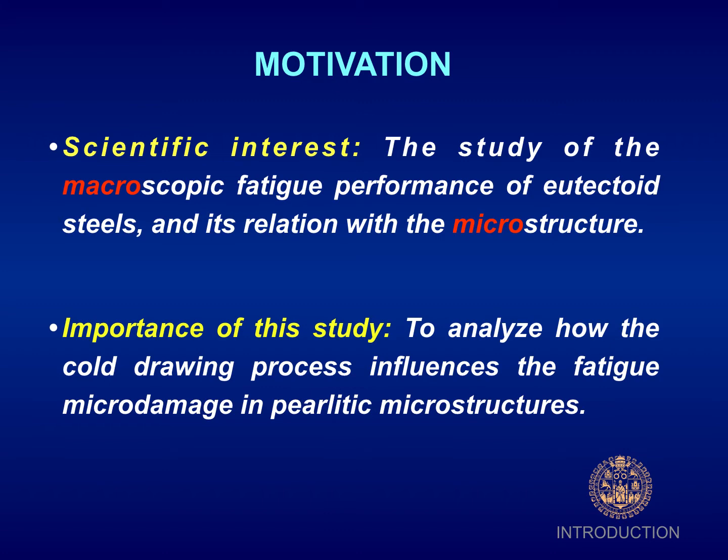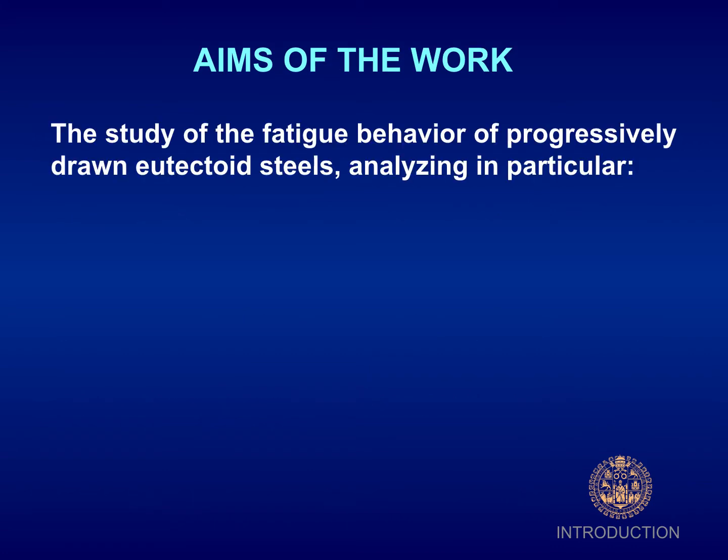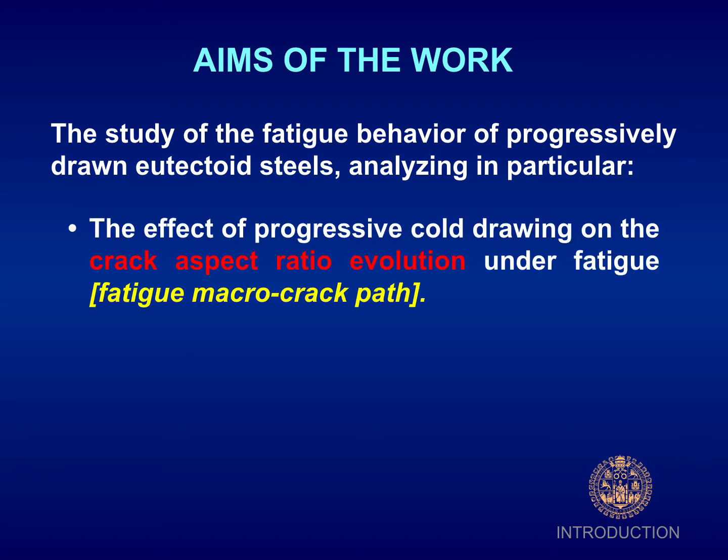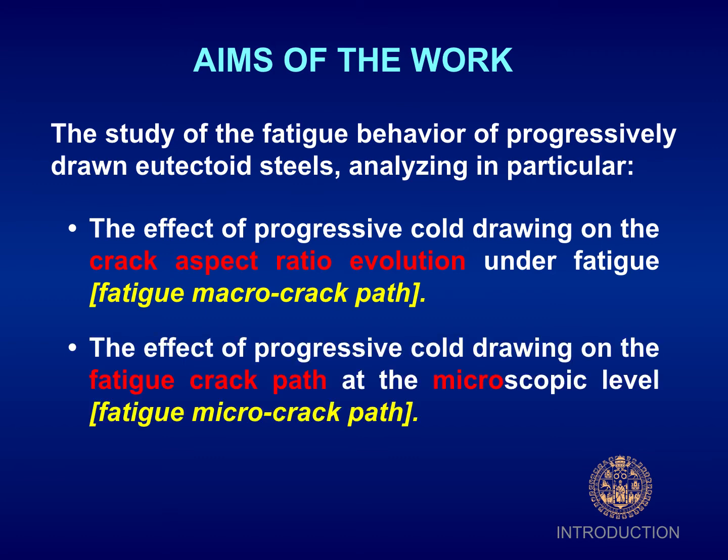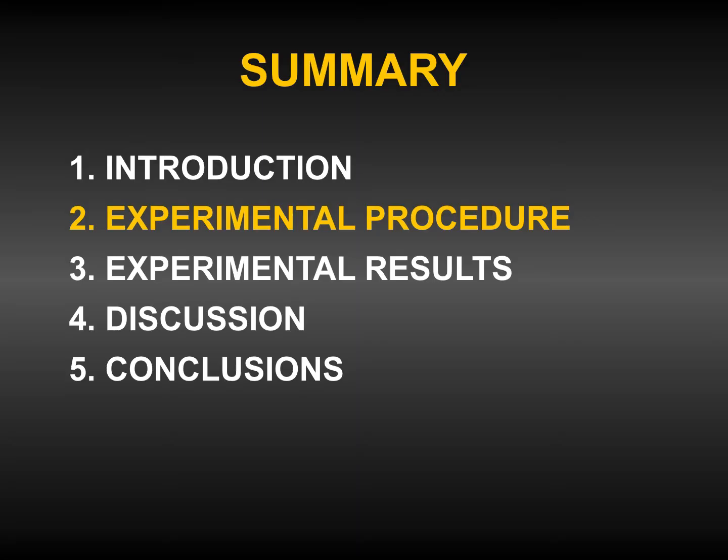The importance of the study is to analyze how the cold drawing process influences the fatigue microdamage in pearlitic microstructures. The aims of the work: the study of the fatigue behavior of progressively drawn eutectoid steels, analyzing in particular the effect of progressive cold drawing on the crack aspect ratio evolution and the fatigue macrocrack path, and the effect of progressive cold drawing on the fatigue crack path at the microscopic level, the fatigue microcrack path.